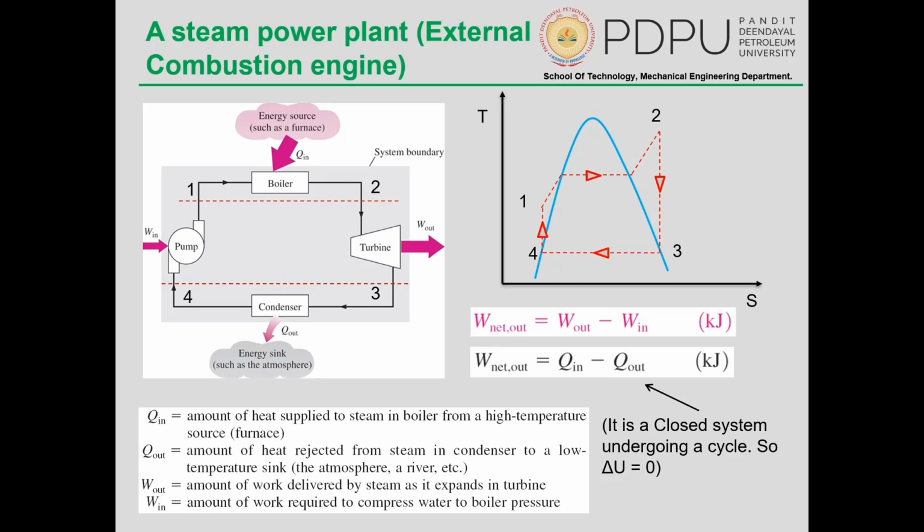Okay, now moving ahead, we can see that all these processes follow a particular path. If I want to draw, I can draw a clockwise rotation circle indicating the clockwise rotation of these processes. Whenever from now onwards you see a circle with an arrow representing a heat engine or a refrigerator or heat pump, we will be very careful of properly drawing this circle and arrow. This clockwise rotation is an indication of positive work, basically indicating we are going to get work out of this particular cycle.